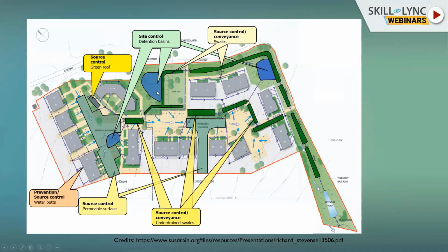Apart from these rainfall events, the basins were mostly dry. Then the very last was the regional control: a very big retention pond at the very outlet of this township. As we discussed, these big ponds should be away from the urban area. So, meeting that criteria, we proposed this retention pond here. Any excess water from the site can come here and be stored.